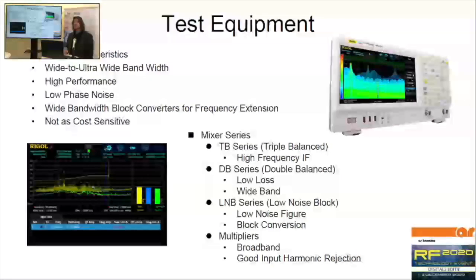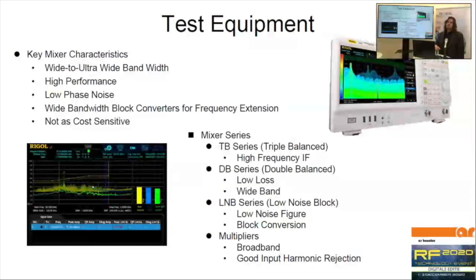Test equipment. Well, we have a lot of test equipment, and probably some of the presentations will get into this topic. But usually a spectrum analyzer is pretty wideband. Multi-octave, most of them work from 9 kilohertz to way beyond the gigahertz versions. So you want your mixer to be very wideband. You want them to be low phase noise because you want to measure that.